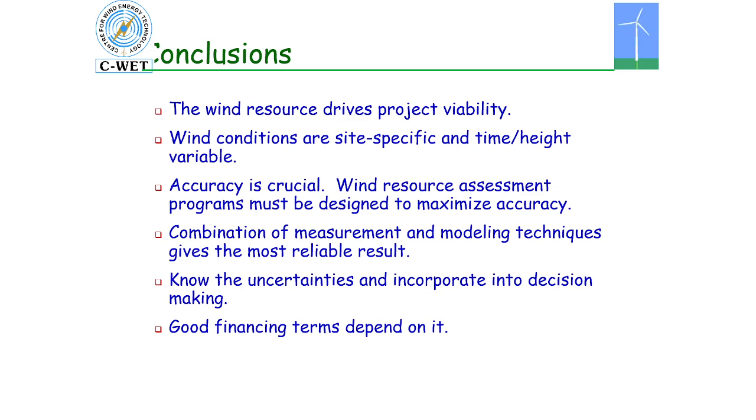That means, is it done as per the IEC standard, the wind mast measurements? Is it done as per the data analytics procedures given by IEC? Then it becomes a bankable measurement. Met mast based measurement is bankable measurement. Modeling based measurement is not bankable, they will say. That's why high accuracy is required for a large project development. It is better to put one met mast and measure for at least 1 year.